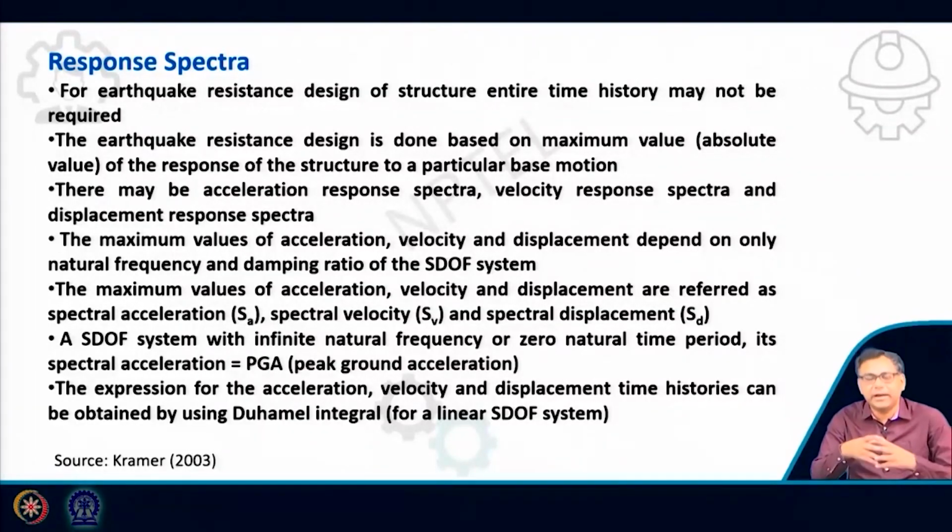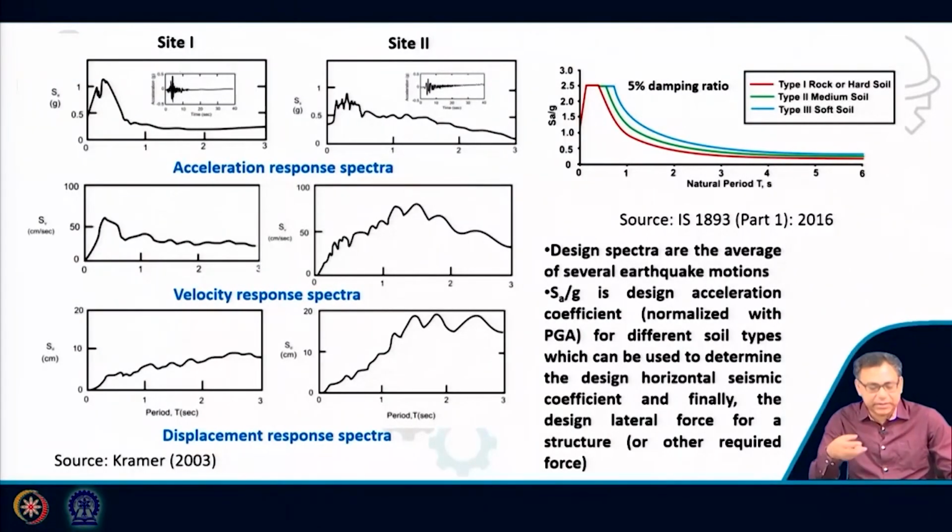So, for any base motion, if you get the expressions by using the Duhamel integral for the acceleration, velocity and displacement, and take their maximum values and plot them, then you will get the acceleration, velocity and displacement response spectra.